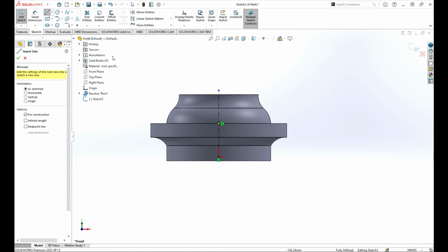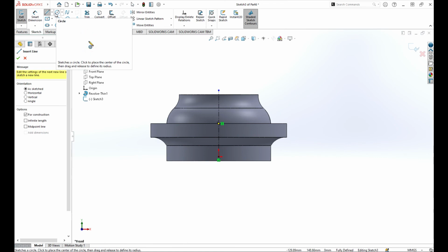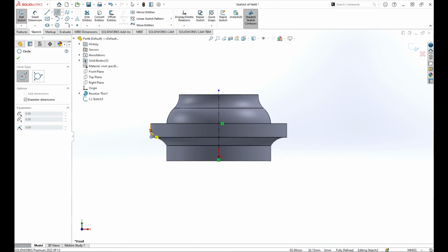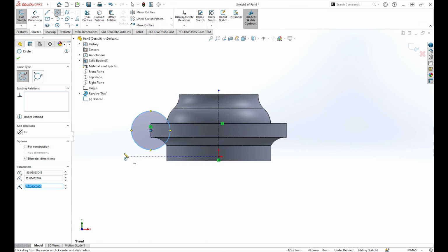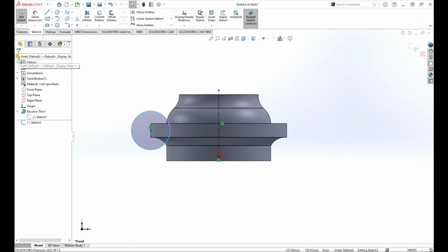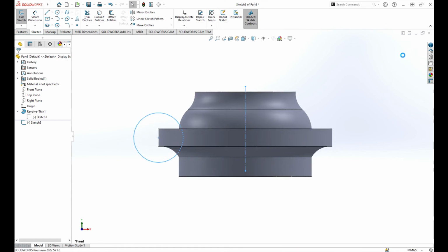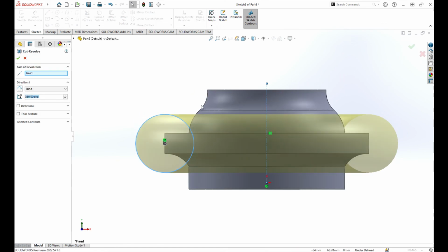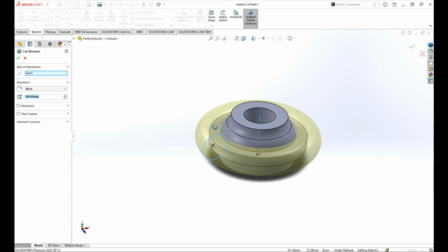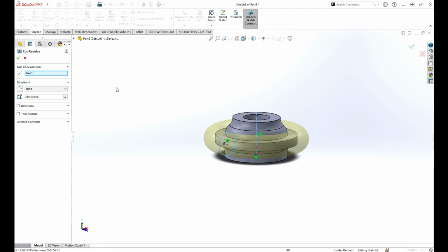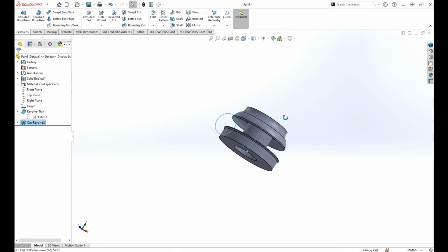After drawing the axis of rotation, depending on the shape you want to cut, or the shape you want to have after doing the revolve cut, here we can have a rectangle, you can have a circle, whatever shape you wish. For this reason, let's have a circular cut. And remember, the thin feature was applied to this body initially. That's why you can see the inside is hollow.